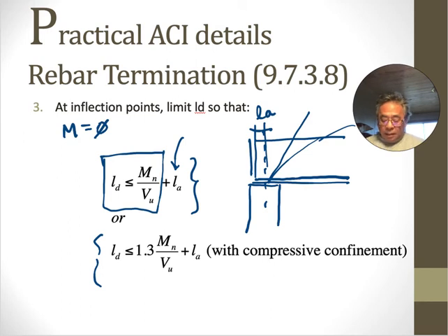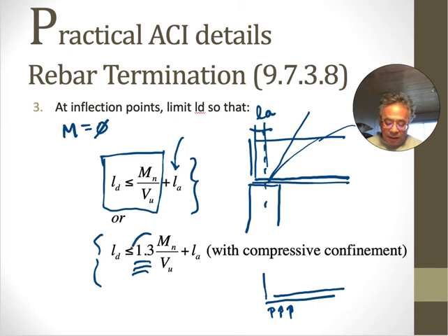Okay. Now, here, this thing here, let me try to draw this again. So here's that beam, and this support is pushing up on the beam. And what that does, it's increasing the friction, right? So if you're pushing on something, it's harder to slide out. And so it'll give you more bond, and you can have a shorter development length. And so you get that bonus here.